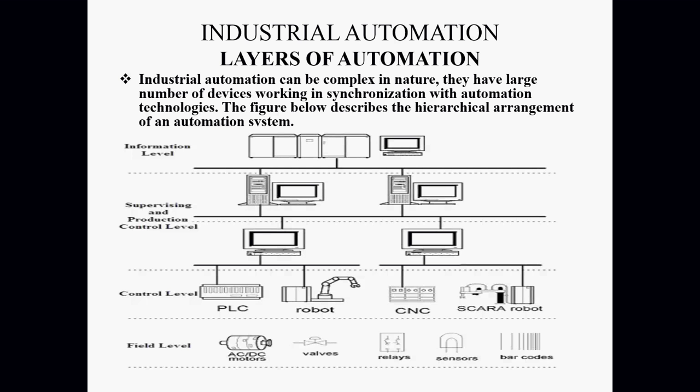It follows the logic. So whatever inputs it senses from these field devices, it puts them in evaluation with the logic that is written there, and based on that evaluation takes necessary actions, which result in your output commands, which again go to your field elements and decide the course of action for them. So if I've written my logic correctly, then the valve will close. If I have by mistake written my logic incorrectly, then the valve will open, right? So this is your control level.